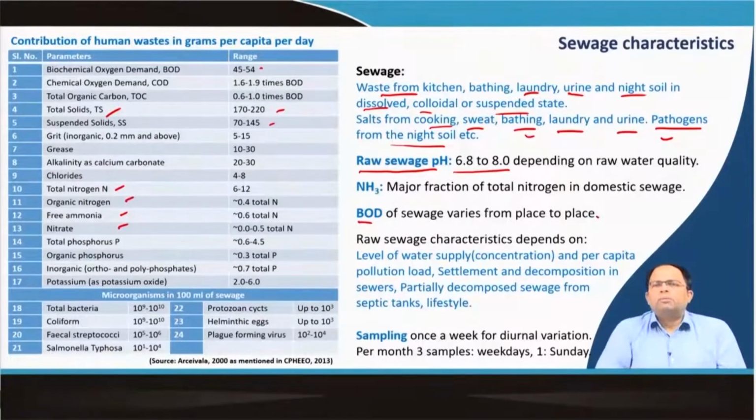If you remember from one of our earlier lectures, we calculated how adding more sludge from a septic tank into the sewage treatment plant affects the BOD loading of that plant, and whether the plant is able to reduce that amount of BOD. So, every plant is designed to remove a certain amount of BOD and total solids.